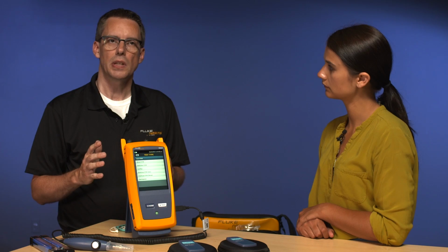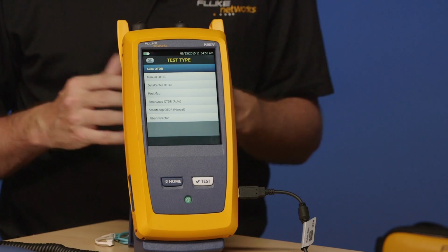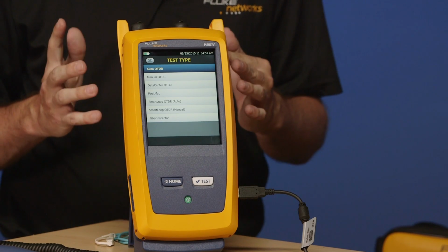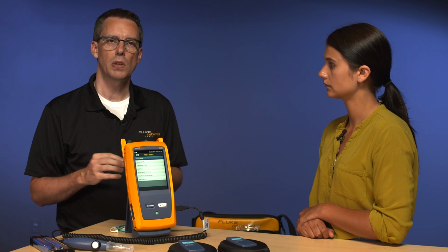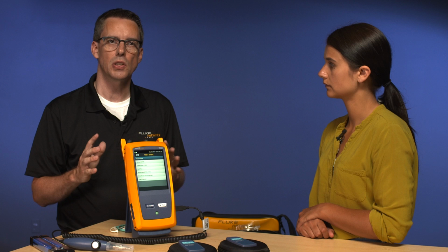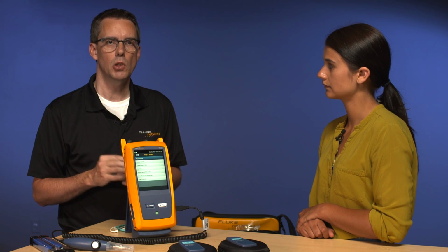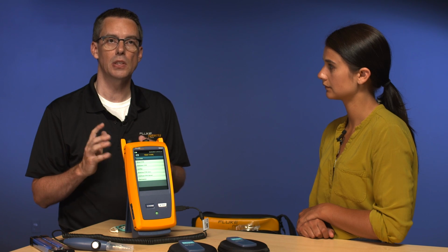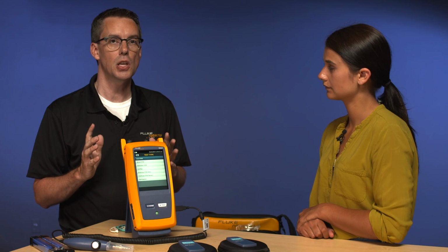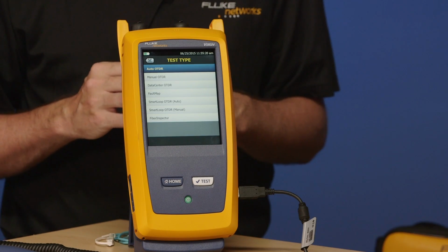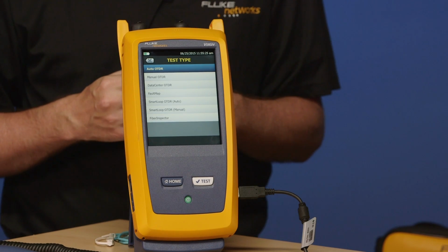We're not going to do all of these today, this is just a getting started video. The first option on here is Auto OTDR, which is one of the most common settings. The reason why is if you leave it in Auto OTDR mode, it will decide what the pulse width, the averaging, and all the ranging, and all the other stuff that you typically manually have to set up. Now, if you're an OTDR person, you may not like Auto OTDR and you want to set this up yourself, you want to set your ranges and your pulse widths and your average time yourself. That's totally fine. Second option on the list here is manual OTDR.